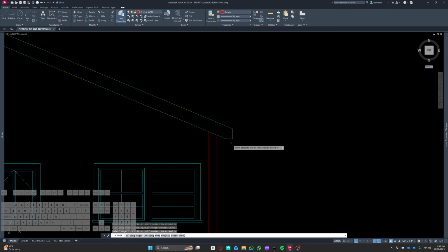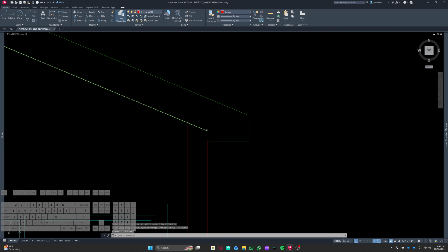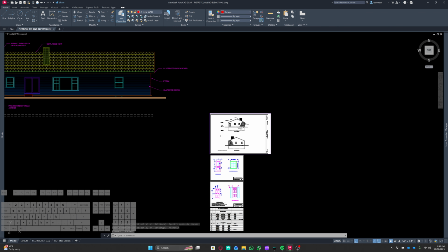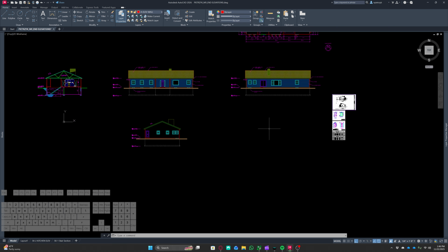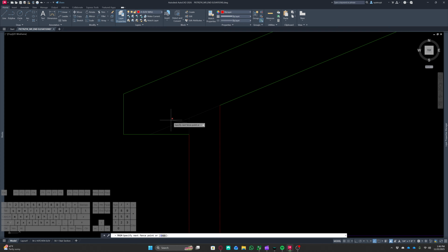Now, a quirk about the roofing is it doesn't do this. It actually will connect in because we have our soffits. So I will do something as simple as this, where I just make sure I have this kind of end piece. I can double check on my drawing, and this is what I want to see. This is how it needs to be. Again, I'll do an extend, trim out this guy, then this guy, bring up a line, match properties, just like so.